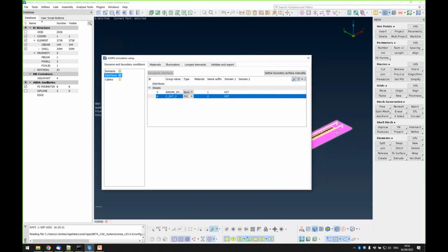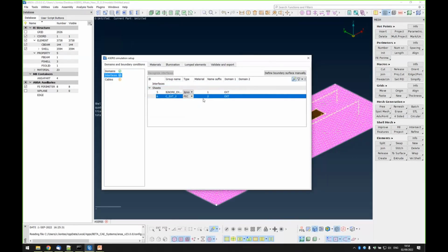And I want to simulate only this ground plate. Okay, so this type is PEC. I could also change its type to make it resistive, but then I would have to choose a resistive material. Okay, let's keep it PEC.